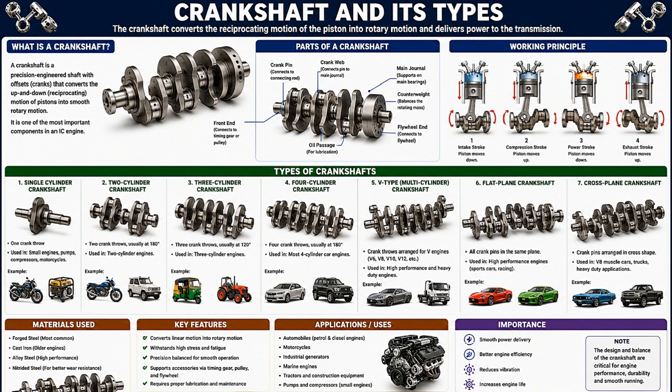Now look at the working principle section. This shows the four-stroke engine cycle. First, intake stroke. The piston moves downward, drawing air-fuel mixture into the cylinder. Second, compression stroke. Piston moves upward, compressing the mixture. Third, power stroke. Combustion occurs.